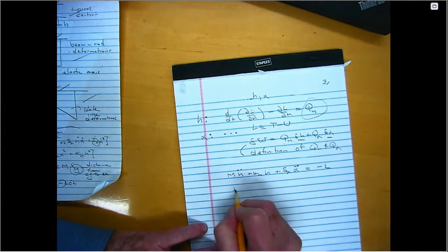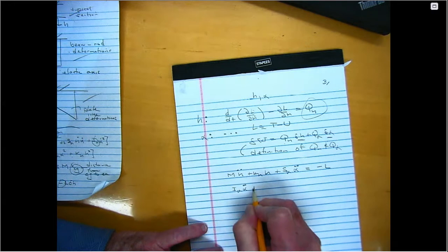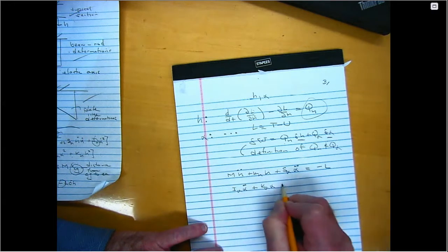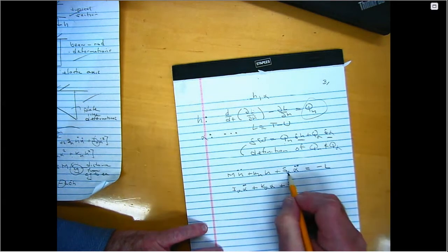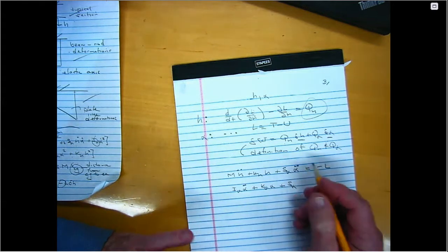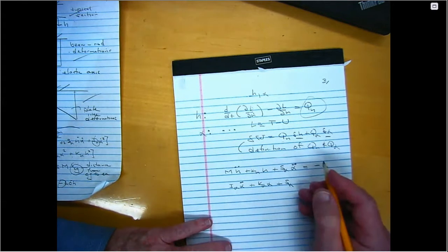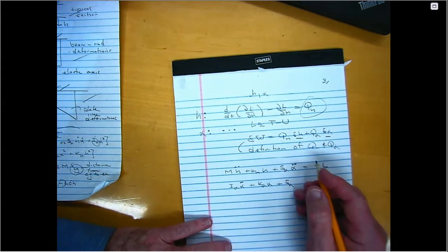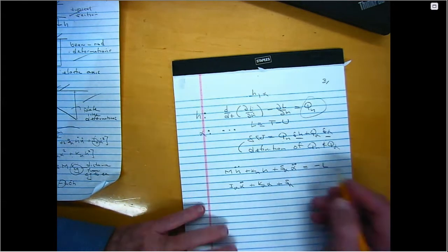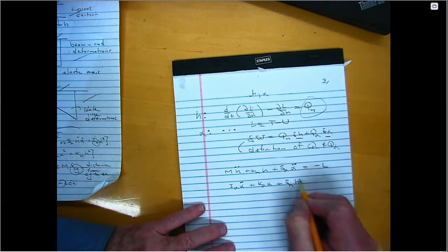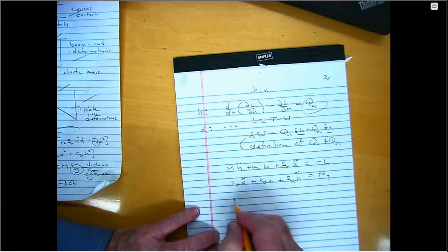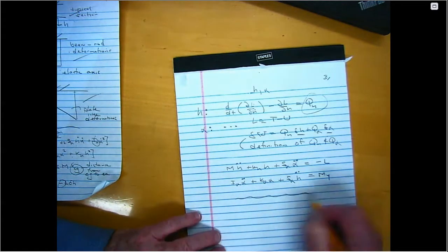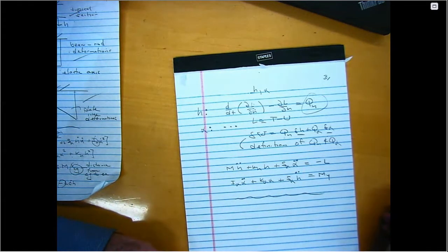And then you have I sub alpha alpha double dot plus K sub alpha alpha plus S sub alpha h double dot equals M sub y. I don't know why they don't call it S sub alpha h, but they don't. In the literature, it's always S sub alpha. Seems like they're not giving proper recognition to h. Okay? And now the remaining thing I have to do is write down some expression for L and M sub y.